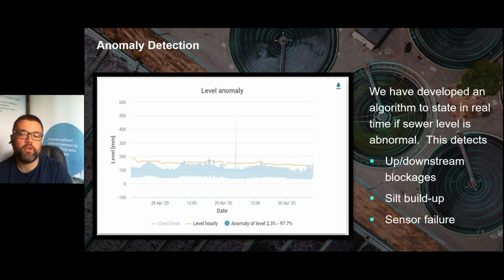But that dry matter, if it goes on for too long, can cause the start of blockages and can cause the start of issues. And we can look at this type of trend and we can couple it with an event system which says, okay, yeah, it's out of band, but it's not a problem yet. You can actually start to categorize it. Okay, how far out of the band is it? How long has it been out of the operational band? And when you start to hit a critical threshold, where maybe it's 100 millimeters or 200 millimeters above the band, and it's been out for 1 week or 2 weeks, you can actually use that to trigger an action.